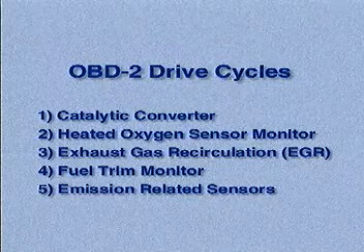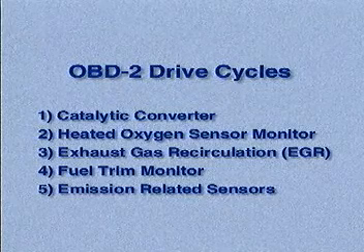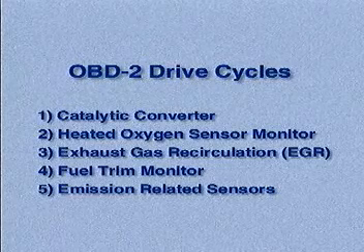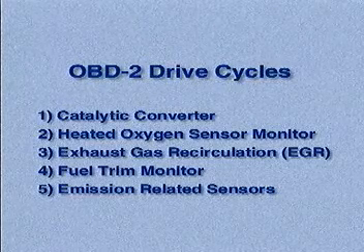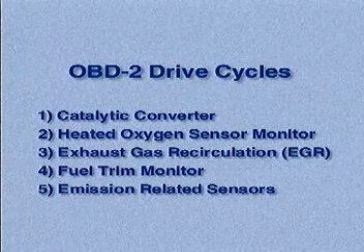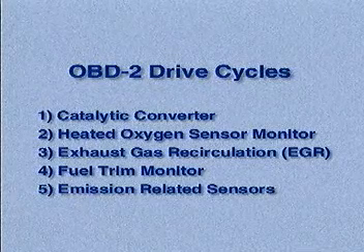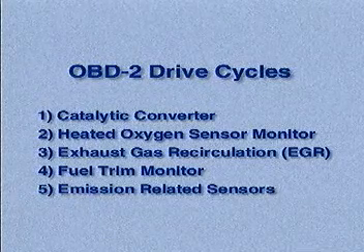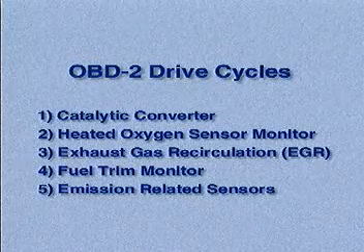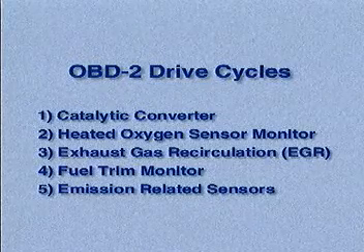Verifying a repair with the 1997 new models will be faster because the OBD2 drive cycles have been broken into 5 different drive cycle patterns, depending on which systems are to be tested. The drive cycle patterns were designed so that the engine operates under the best conditions to monitor the performance of the particular system you need to test. This is going to make your life easier, so let's step through each of these tests.